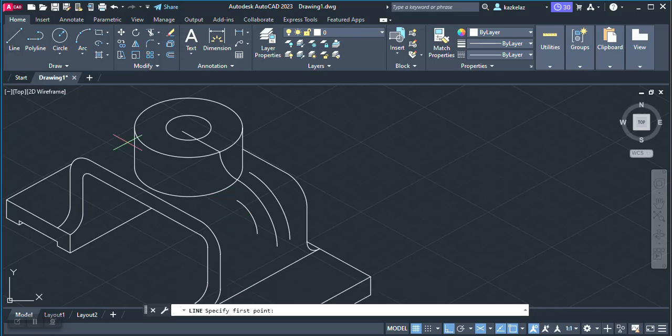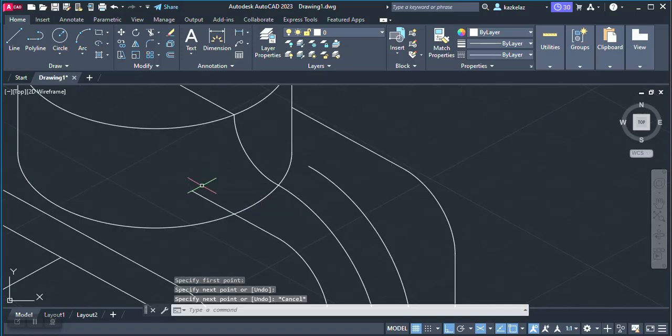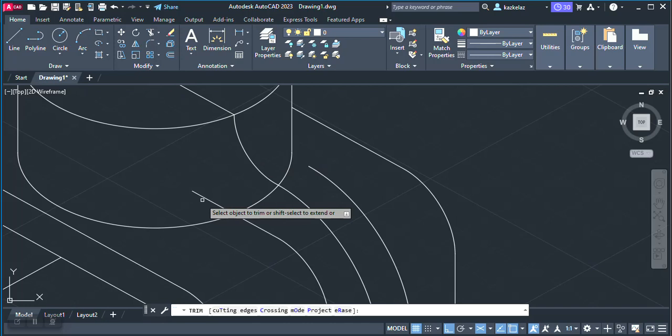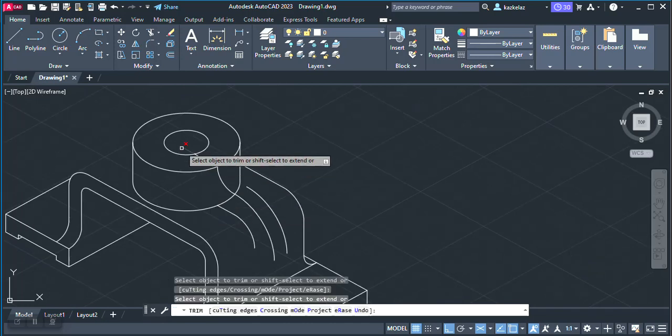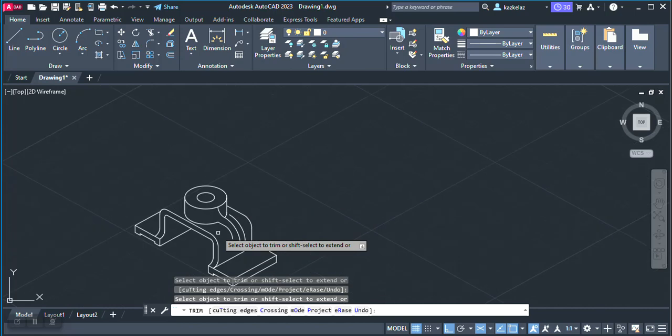From there we're saying 39, we change to that arc, something like this. We don't need two of the lines, just copy the other one. We'll also trim there, and then we copy this line to a distance of 10 and there. Okay, so now we need to trim that part there.